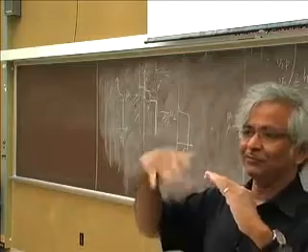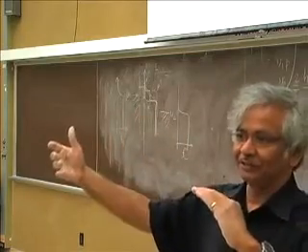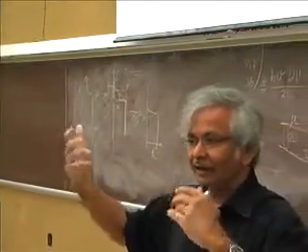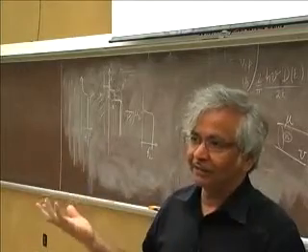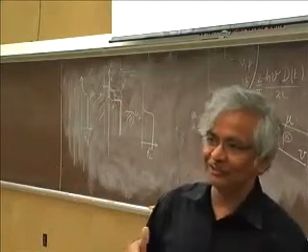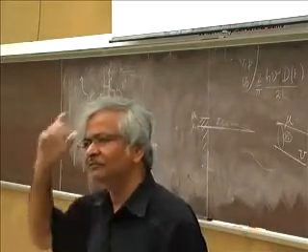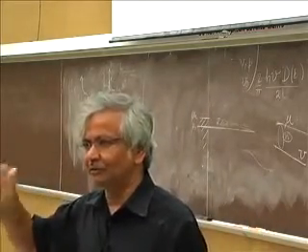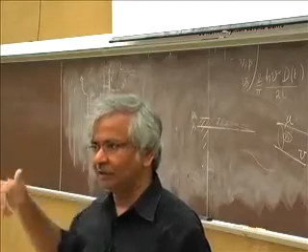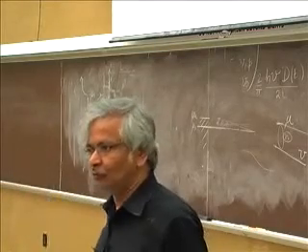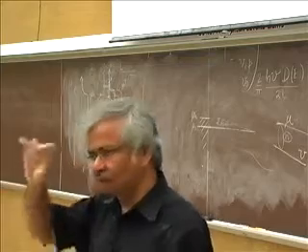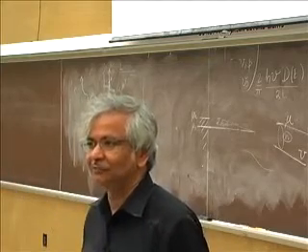But if your objective is to model a conductor at room temperature, then in most cases you are better off using a semi-classical picture. And I'd say that almost the only reason to go to the quantum is if tunneling effects are important. There are all kinds of barriers where, like Mark also showed how for the 4 nanometer MOSFET, there were all these tunneling things that needed to be accounted for, right?